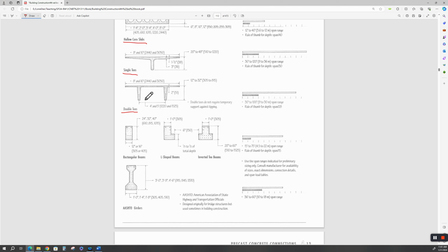Now, this was real popular to use these T's, these double T's, as walls. There were two mid-rise buildings off of the 59 freeway back in the 70s and early 80s, and they may still be there. I don't know. I don't live in that area. The architect used these as the walls, and then he had holes precast in the flanges, and these would be sticking out for all the world to see. And then the window system would be either in holes in here or over here, or they'd space them.